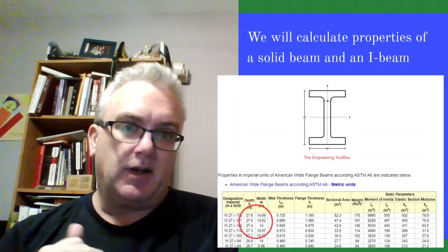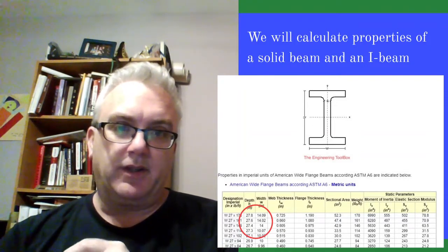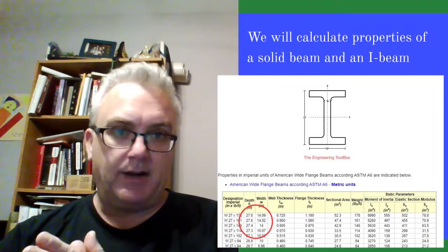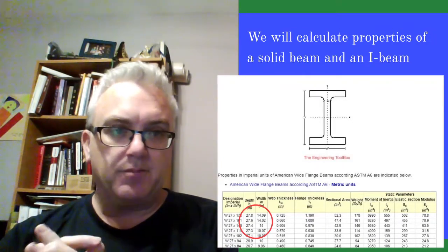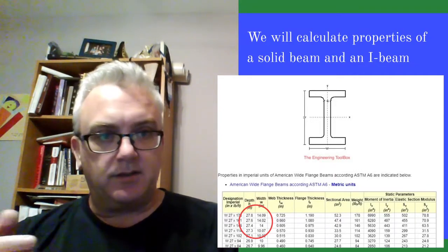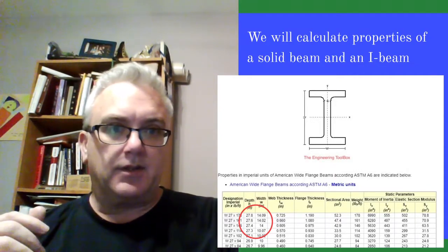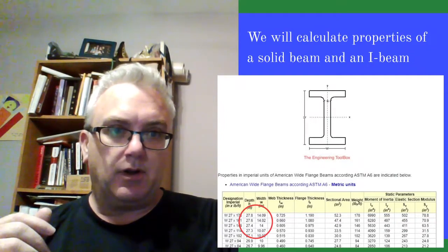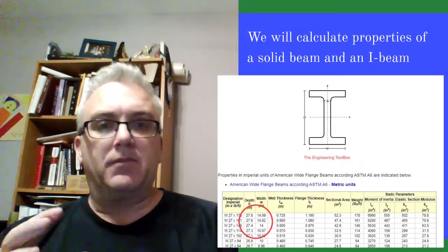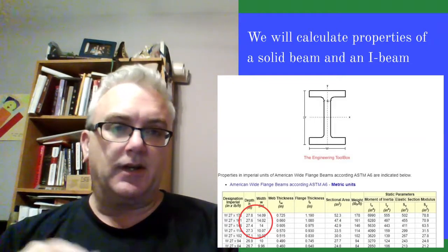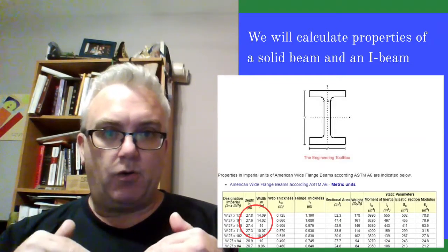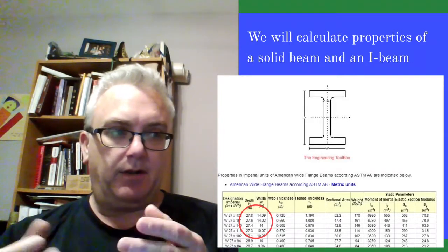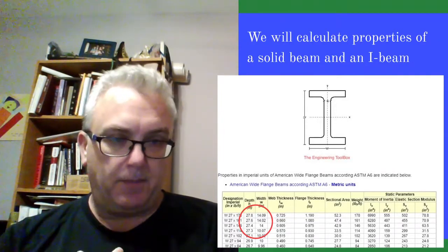Now the I-beam, as you all learned during the quiz last week, which was to read some articles on I-beams and to learn a little bit about them, has some distinct characteristics. There's the web, that's the piece in the middle, and the flanges on top. They're designed to be used in that configuration, and they're designed to hold a lot of weight and to not have a lot of twisting motion on them.